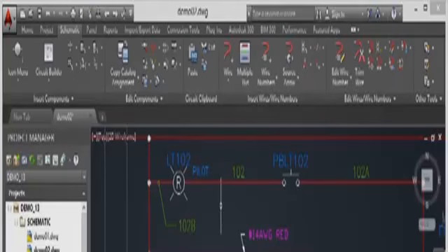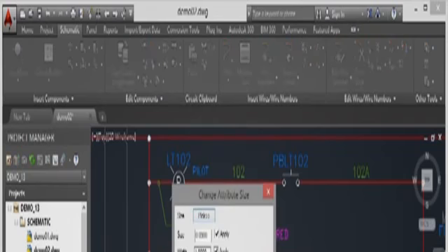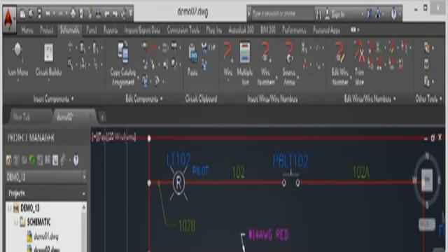So it did change size. However, I didn't actually set that 0.09. It's just a default value. So let's go through that one more time. What I'll do this time is go up to here and go to change attribute size from the ribbon. And I'm going to leave that 0.09 there. And then I'm going to go to single again. And I'm going to go 1 and 2 and then enter to finish.